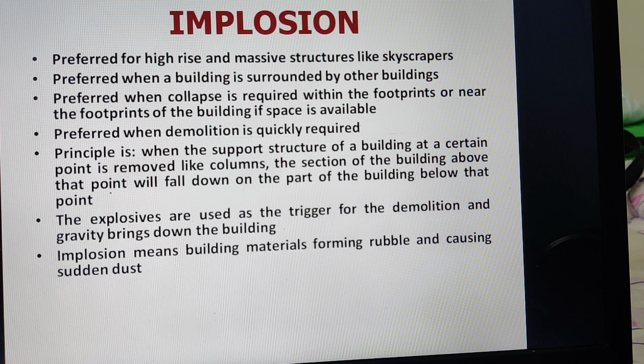This implosion is preferred for high-rise and massive structures like skyscrapers, preferred when a building is surrounded by other buildings, preferred when collapse is required within the footprints or near the footprints of the building if space is available like parking or open space, preferred when demolition is required quickly.